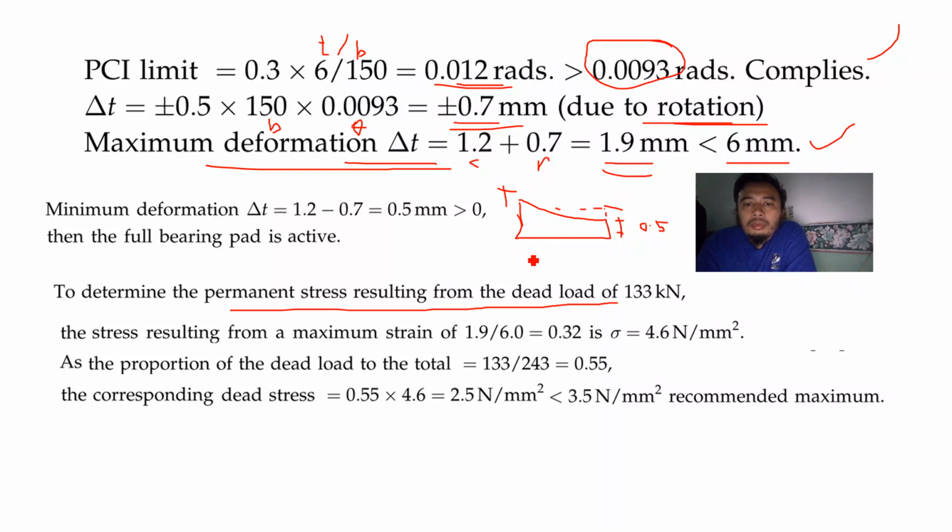So you have your 78 kilonewton self weight, and then you have another one, your dead load, which is 5 kilonewton per meter, uniformly distributed, and then times the span will be 11, so 55 plus 78, you get 133 kilonewton.